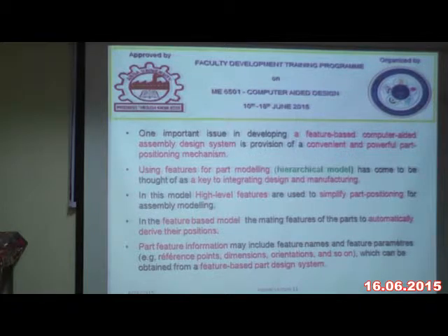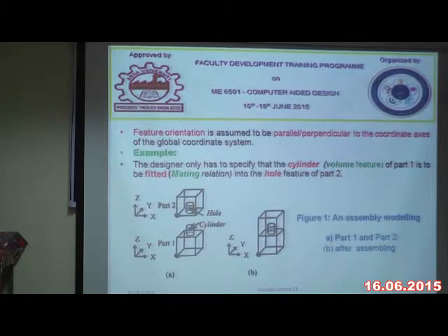Reference points. Reference point means each and every part location with the coordinate, and then dimensions of the part, and the orientation. Orientation is nothing but a direction. After location, the direction of the part should be mentioned, and so on, which can be applied by the feature-based part design system. Next please.